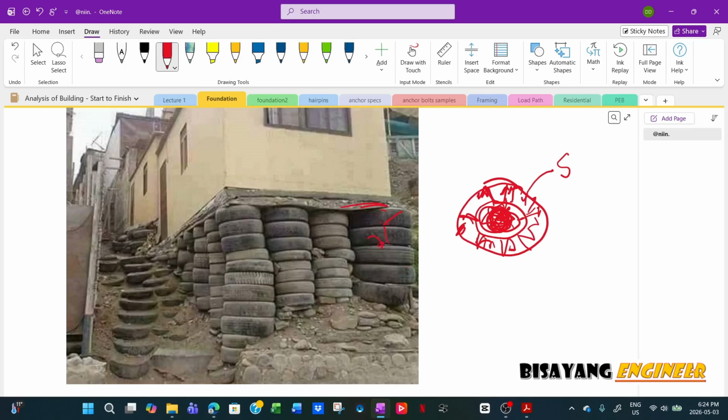And then you just design the slab based on the stiffness of the foundation, then you are talking about a subgrade. That's your modulus of subgrade reaction, right? So the slab will be designed as a grade-supported slab with subgrade reaction. I don't know how to quantify the subgrade reaction based on the stiffness of the tire, but hey, it works.